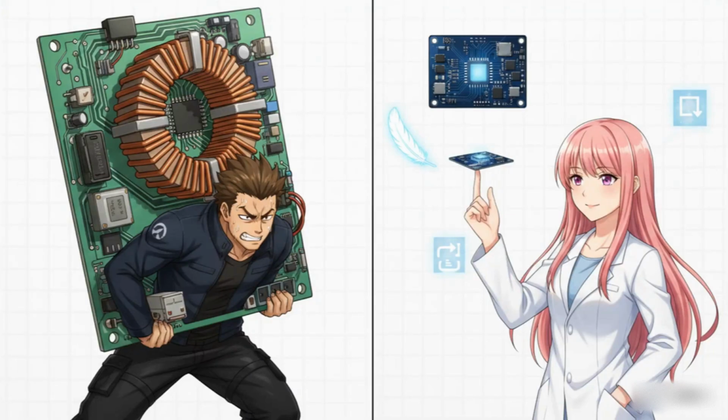And here it is. With active filters, you can design almost any kind of filter response you want without using any inductors. Now, why is that a big deal? Well, inductors are often physically big, they're bulky, they're heavy, and they can be expensive. By using clever op-amp circuits instead, we can get the same results with just tiny resistors and capacitors. That means smaller circuits, lighter products, and often much cheaper devices. It is a huge, huge win.